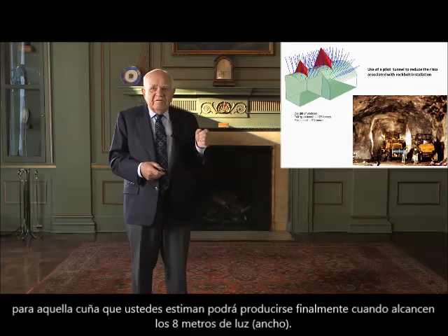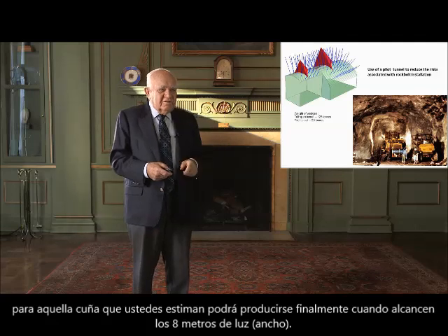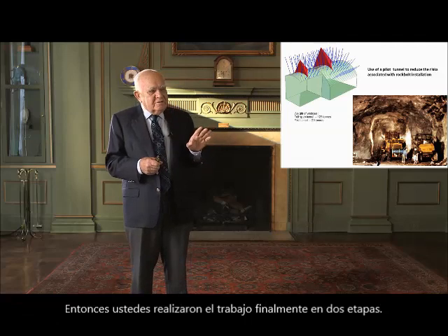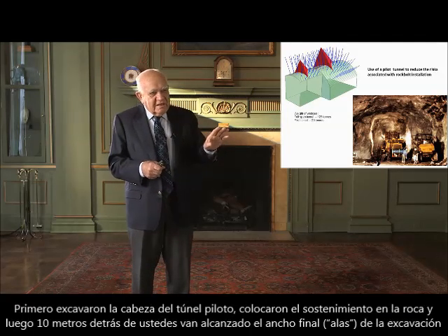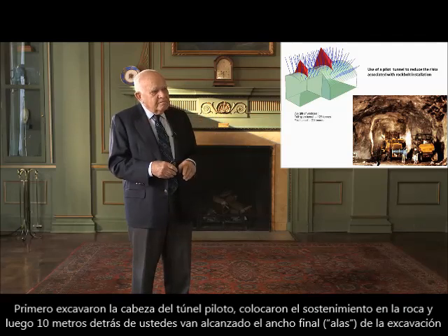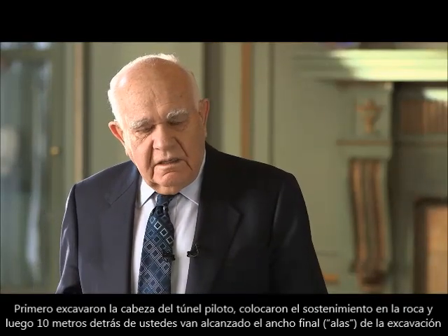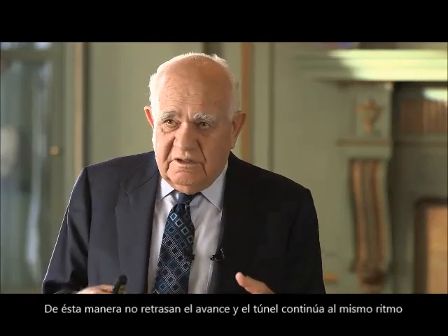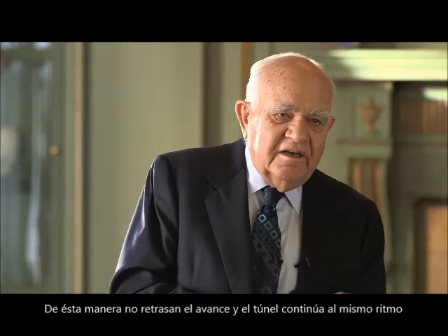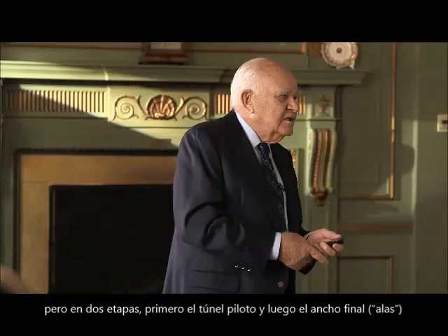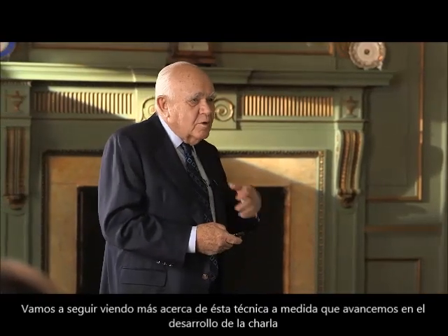But you put the bolts in for the final wedge you're expecting to occur when you open it out to 8 meters. So you do it effectively in 2 stages. You drive the pilot tunnel ahead, you support the rock over your overhead, and 10 meters behind, you drive the wings forward. So you're not impeding progress, the tunnel is still moving ahead at the same rate, but in 2 steps, with the pilot tunnel and then the wings. And this is a technique we'll see more and more of as I go through the lecture.